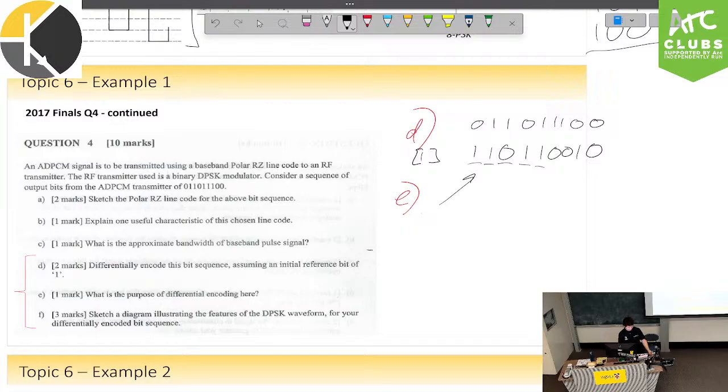Yeah. You can also relate it to a lot of these demodulations, which use phase detection that looks at the absolute phase of your sequence. If you use that, it can be an issue. So with differential encoding, it becomes the relative phase with respect to your previous input. Right. So just for anyone who didn't hear online, it's the conversion of absolute phase as a comparison to relative phase as a comparison.